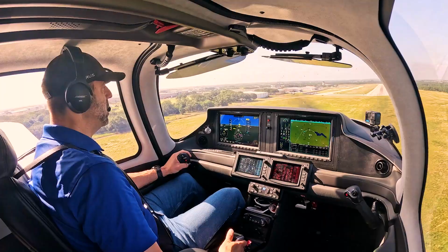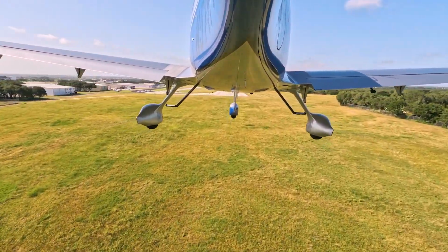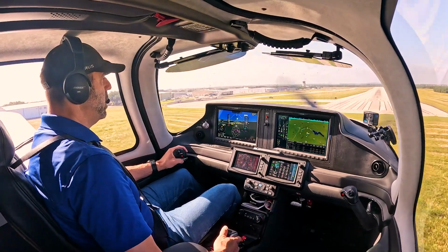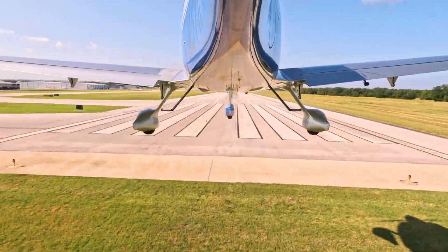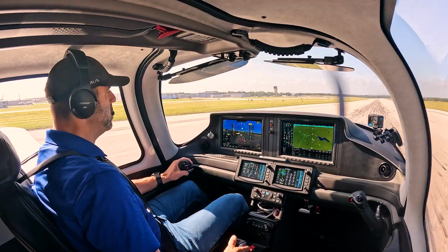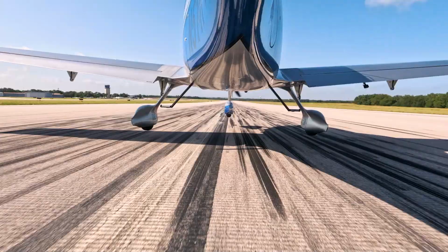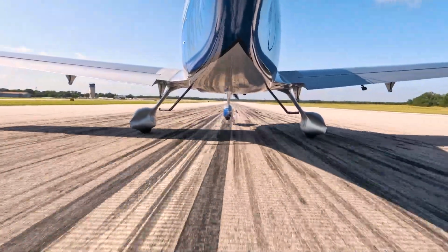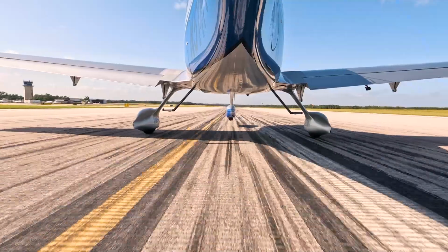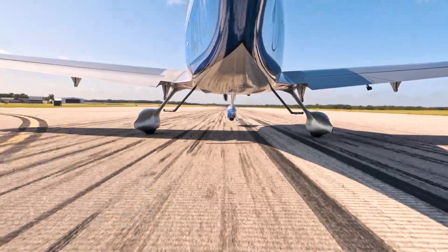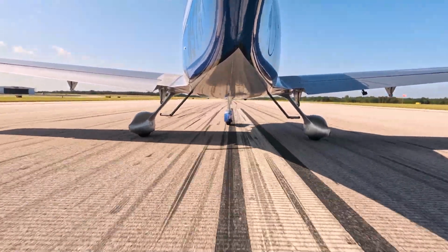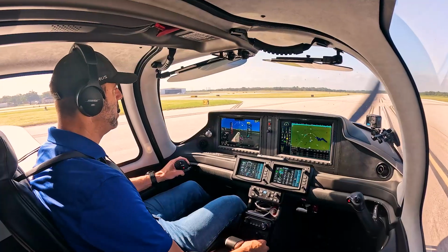Little bit of deflection in. All right. Runway's made, power coming to idle. Right aileron, left rudder. Just as much pressure as I need to stay on center line, aiming for the 1,000 footers. Hold it back, there we go. Let that nose wheel ride. Let off all the pressure, power come back, energy bleed off. There we go. Nice job, guys.